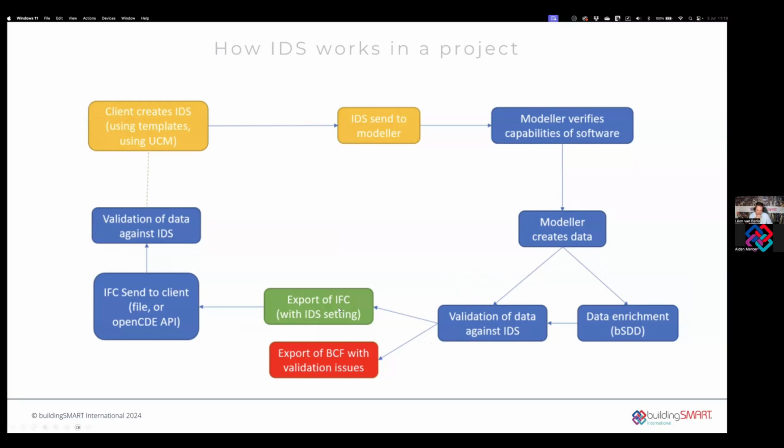Then they export to IFC. If internally the data is not valid against the IDS, you can even have a BCF export with issues. But if everything is correct, it's being exported as IFC.